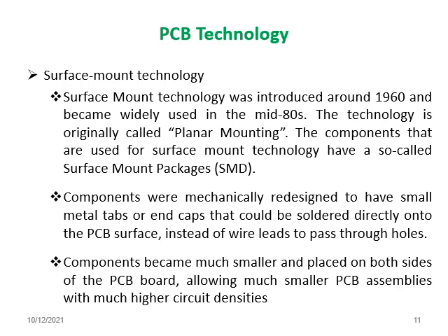And the next one is surface mount technology. So what is surface mount technology? Surface mount technology was introduced around the 1960s and became widely used in the mid 1980s. Before the 1980s, we were not using surface mount technology. In surface mount technology, the electronic components, for example resistor, capacitor, transistor, do not have any leads. Instead of leads, we use a metal cap on both sides of the component.